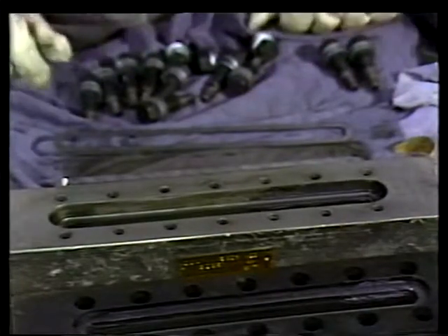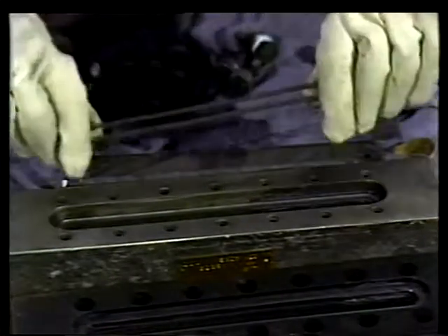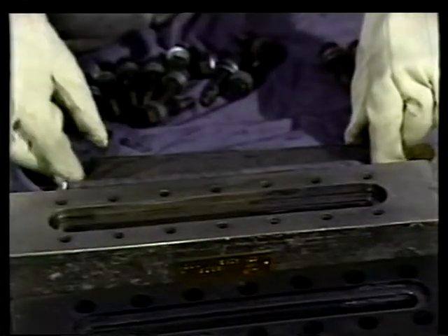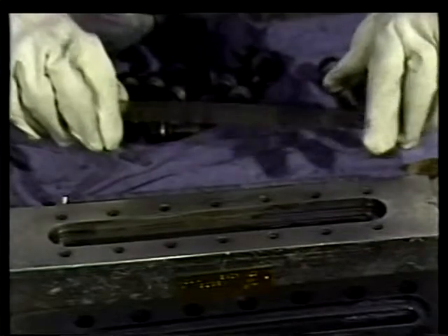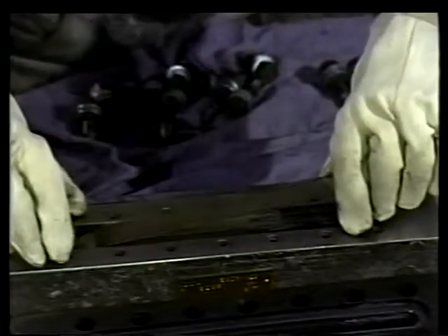Place the gasket in the groove in the gauge body. Then, put the mica over the gasket. Handle the mica by its edges, being careful not to bend it. Usually, new mica is marked with a red dot. The red dot should go towards the pressure side, which is the inside of the gauge.